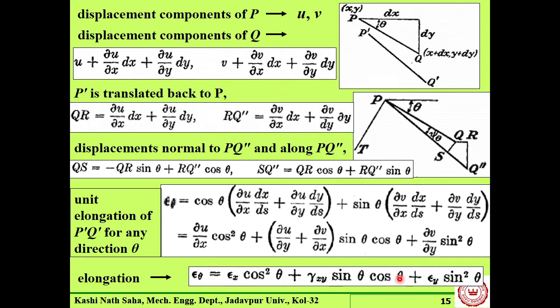Okay. Now here what we know is that the maximum value will occur when gamma xy is 0. That we get from physical reasoning, that corresponding to maximum normal strain, shear strain is 0. That we can find out, or the other way, we can also find out what is the maximum value of this gamma xy. What is this gamma xy? It is a measure of this angle psi of theta, right?